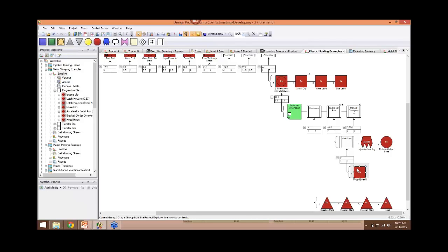This is a part symbol representing the main shot material. This is a material modification symbol representing the injection molding process. Here we can see the number inside the symbol. It means how many seconds will be used for the injection molding process. The operation symbol represents a method to unload the part.